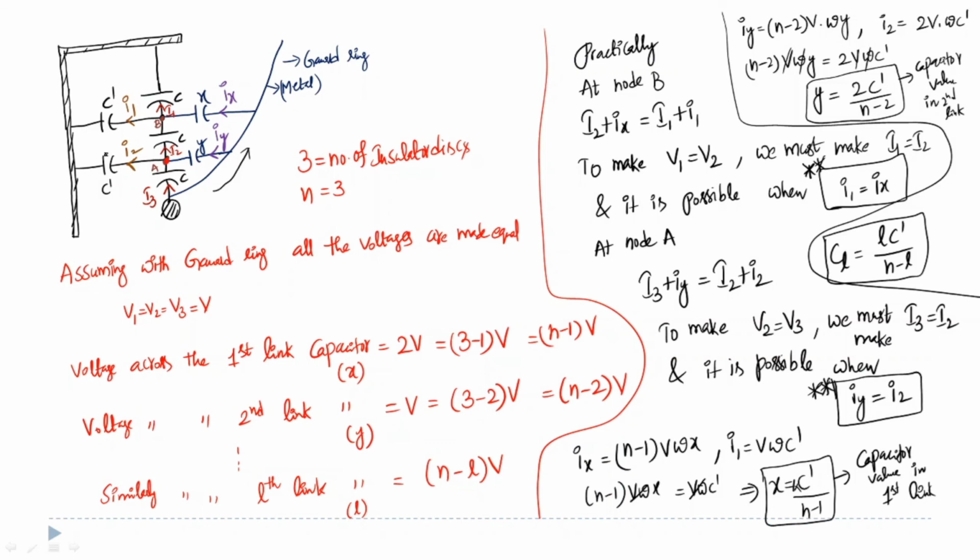by which the voltage across each and every disc remains the same. Okay, so the problem with this method is we need to add one more guard ring, which increases the cost of transmission, and it is very difficult to follow this method, because it is not easy to connect a guard ring to the power conductor for the entire length. So that is the reason why we prefer this method rarely.